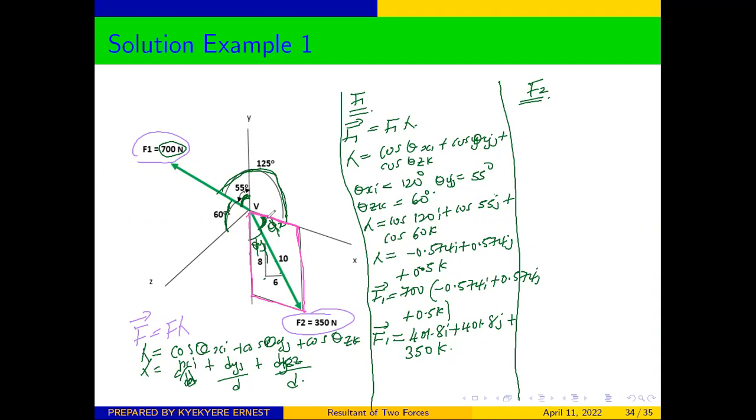So from there, we can resolve our force by using these angles. We have theta x, and we have phi x and phi y. Phi x and phi y represent the angle this force makes with the x-axis and the angle it makes with the y-axis. If we want to get this side, it is adjacent to our angle here, which is phi x.